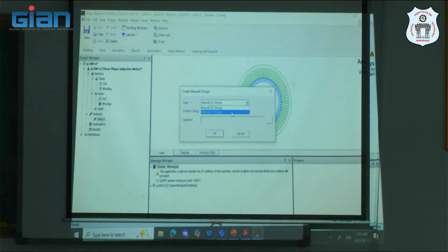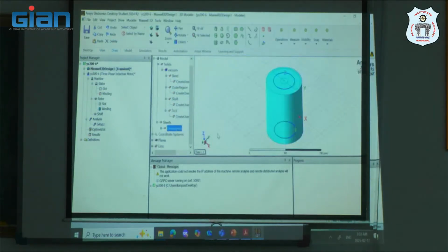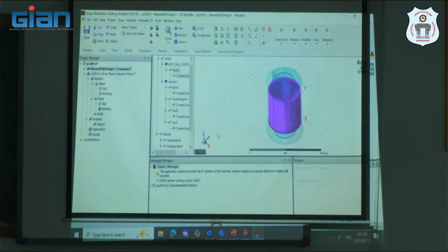Now just looking at it from a nicety perspective, generating a 3D model and clicking OK. Then in a few minutes, the software will generate a 3D motor model for you. It will generate a cage, winding, so it's creating 3-phase windings.